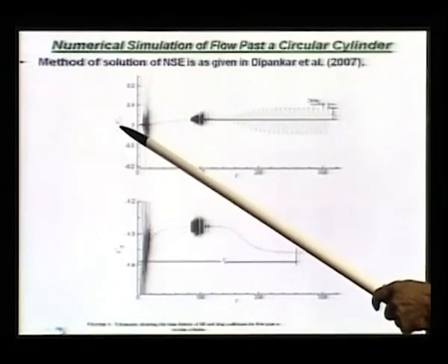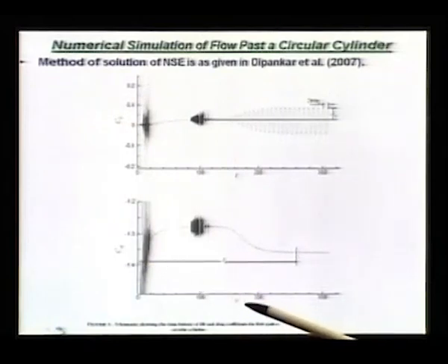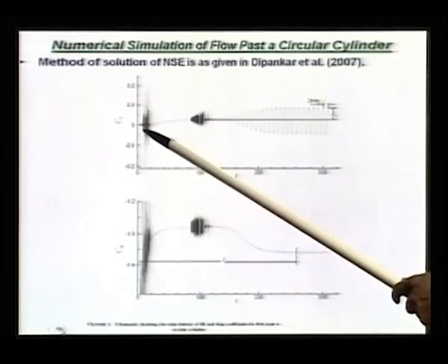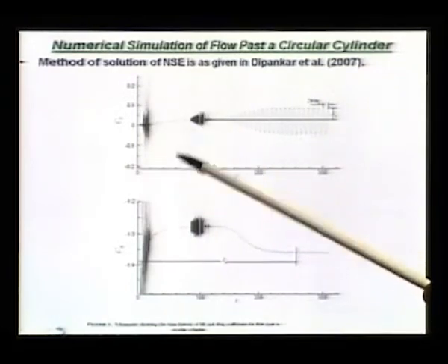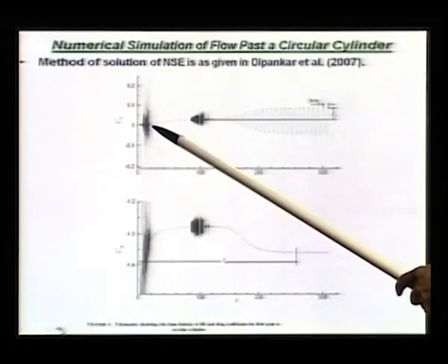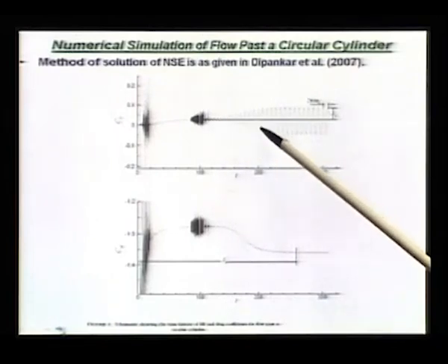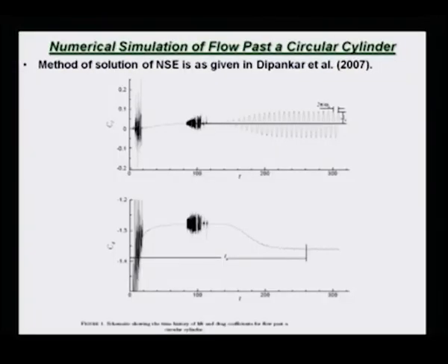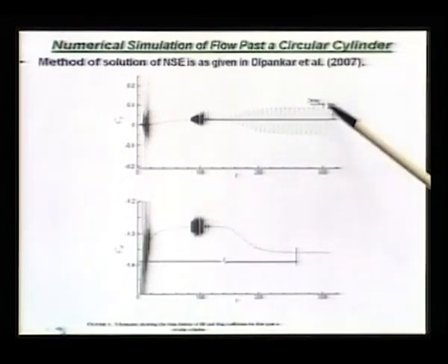What we have plotted here is CL versus time and CD versus time, and what you notice is that CL versus time shows some kind of very high frequency oscillations. But then again that quenches, and then again it suffers that, and afterwards slowly these instabilities that we are talking about pick up and you get to those kinds of equilibrium amplitudes and frequencies, etc.